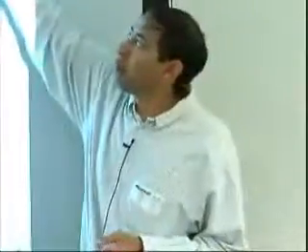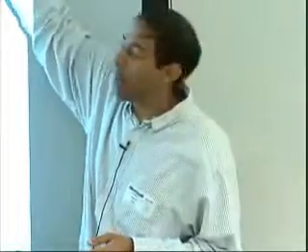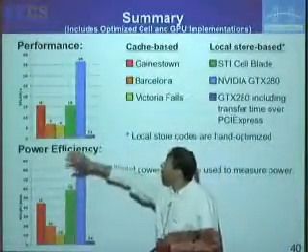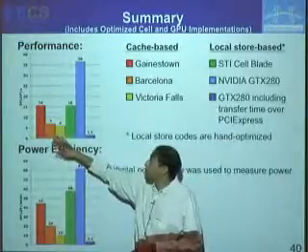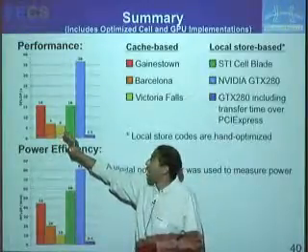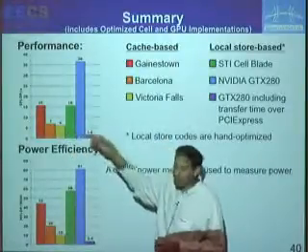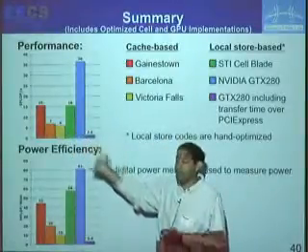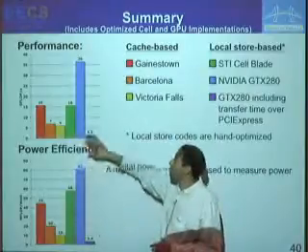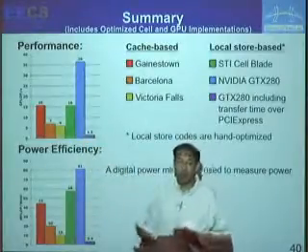But we show both the optimistic upper bound as well as the pessimistic lower bound so that we're more even-handed in our presentation. So what you see here is that the 3 cache-based architectures do, at best, as well as the cell. And the GPU does significantly better if you're not transferring between the 2 memories. If you are, it actually does the worst by far.